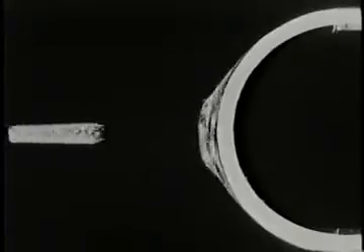The singular point where the central streamline reaches the nose is a stagnation point. The speed is zero there. On both sides of the unique stagnation streamline, the fluid decelerates, but not to zero speed, and then slides around the sides.